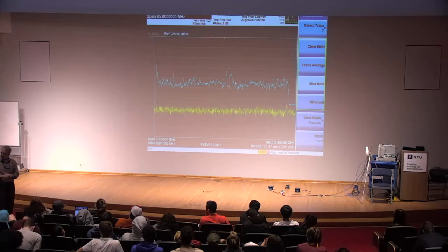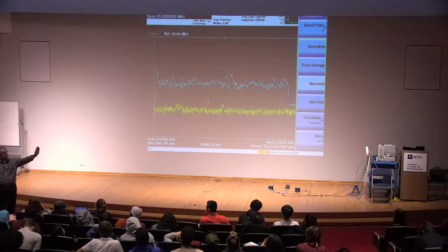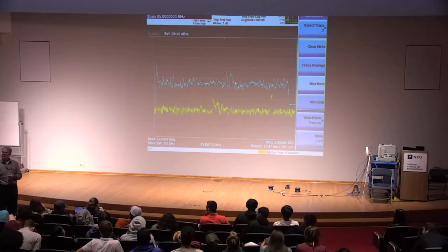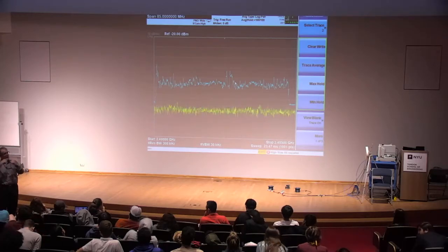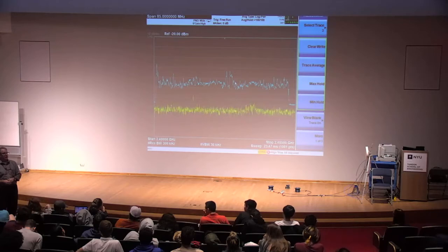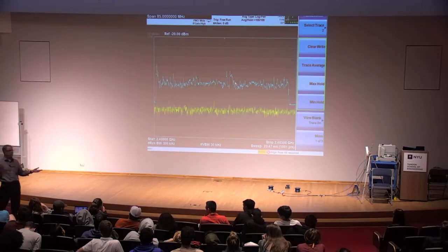Specifically, I'm doing something called full duplex communication. Remember the uplink and the downlink example? There were two separate frequencies. So when you make a phone call, you're really using twice the frequency resource. Every single bit of frequency is spoken for. So if you're using twice, is it possible to communicate both up and down at the same frequency without interfering with yourself? Right now that's been the thrust of my research. After the talk, if anybody's interested, you're welcome to stop up, and we can talk more specifics.